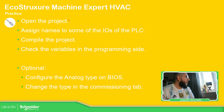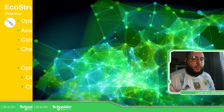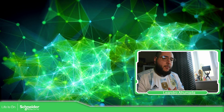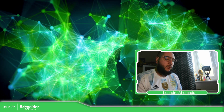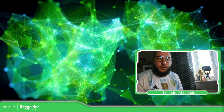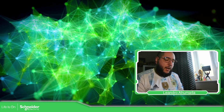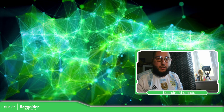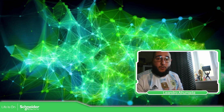So we have already opened the program, assigned the IOs, compiled the program, changed the variables, configured analogs, and changed the modulation type. So we have already covered all of the things that I wanted to show you for the inputs and outputs on the controller. So remember to assign the names for the symbols that you want for each of the IOs. And also, if you're using the analog inputs and outputs, configure the right type that you want for them.